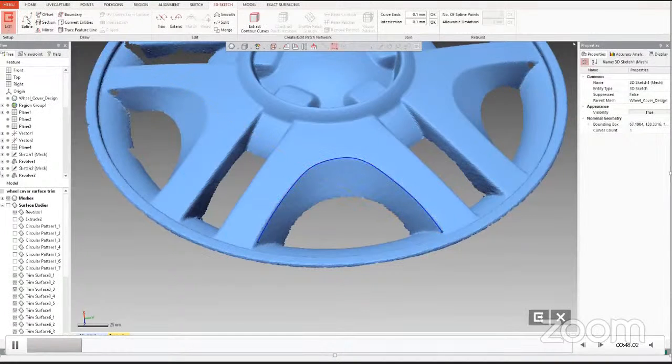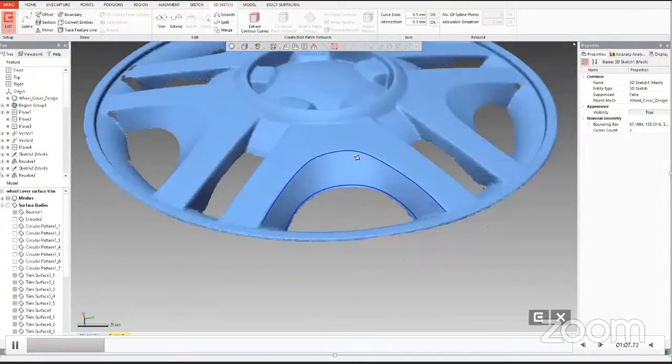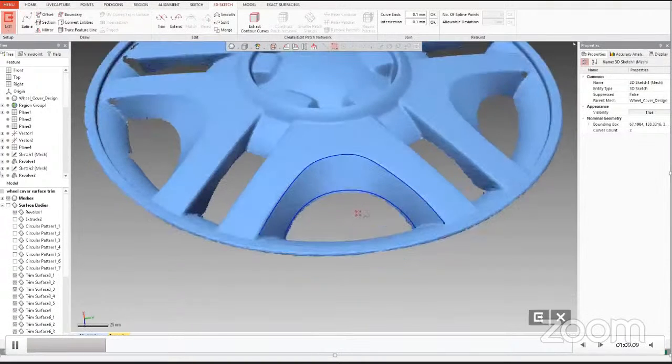All right. Similarly, we want to use the loft command, and for that we must have two sketches. This type of feature is basically made with the help of the loft command. So we will also draw the 3D sketch at the bottom, exit the sketch. Each spline has a number of points in it. The bottom spline had 50, so we convert it to 20 to make it smoother.